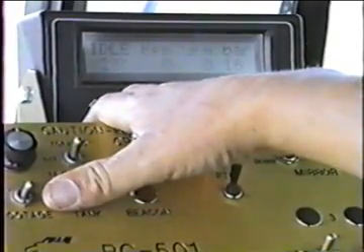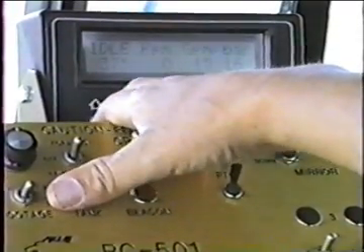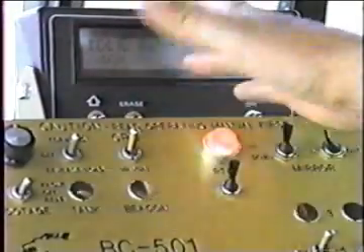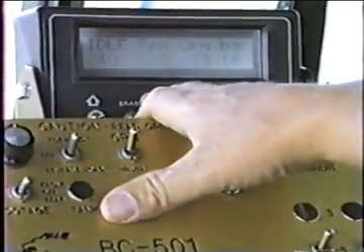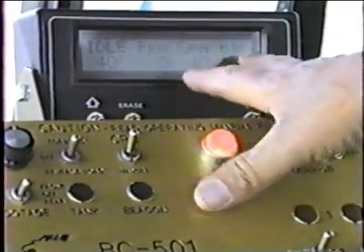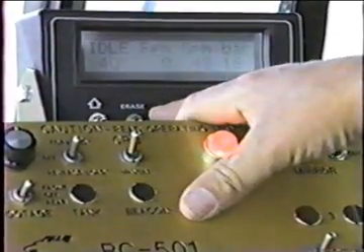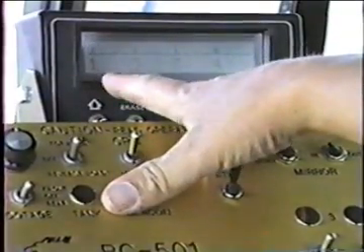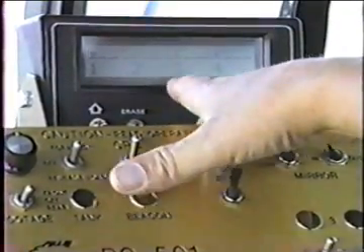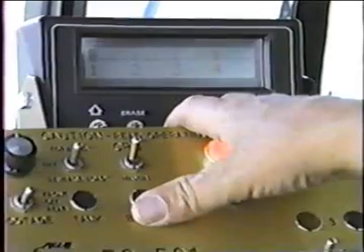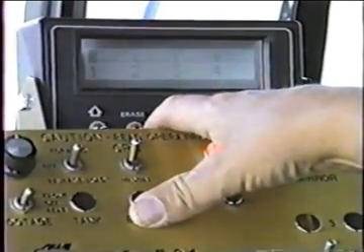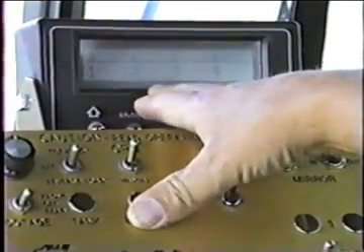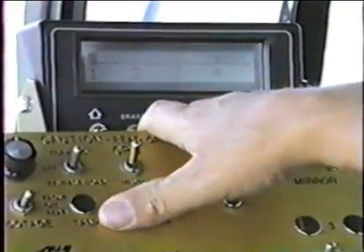Normal speed is about 40 gallons a minute. Good idle GPM speed. Seldom have to change that for any reason. Going through the scales on the computer, pushing the select switch. If we go down again, now we'll see the nozzle size. Nozzle size is a function of how much we're pumping compared to how fast we're moving, and the computer will tell you what size nozzle you should have in it.